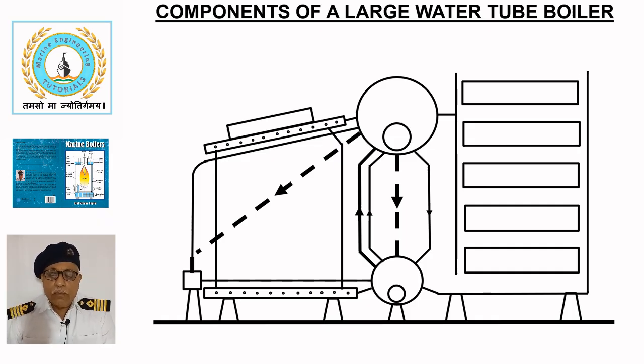In addition, the boiler may be equipped with a superheater, a temperator, and a reheater to control steam temperature for mechanical power generation and auxiliary purposes. An economizer and an air heater are usually provided to recover waste heat and improve plant efficiency. A brief description of these components is given here.